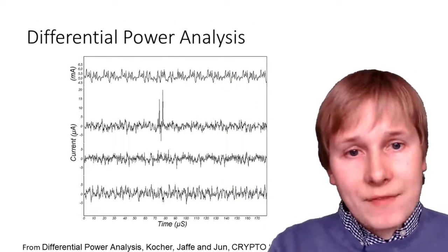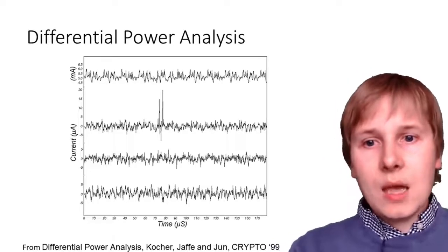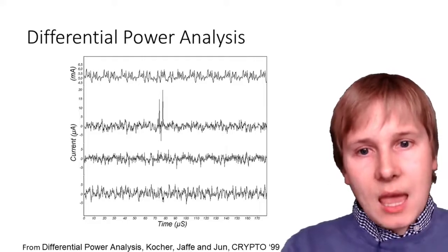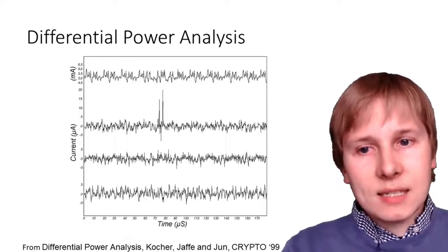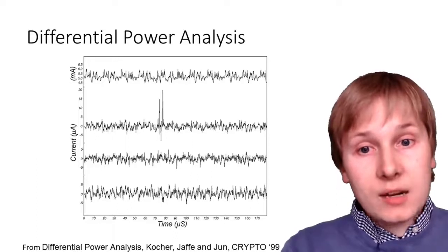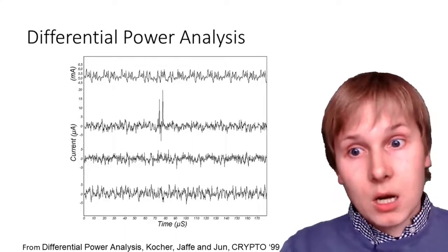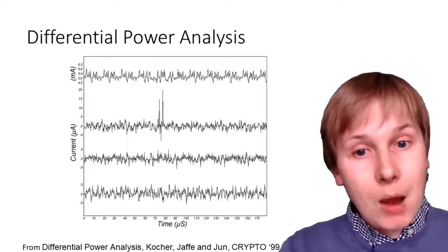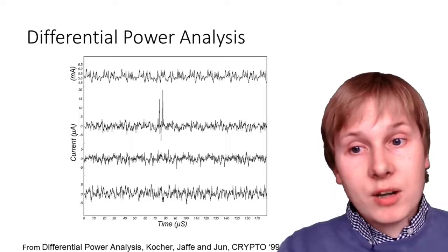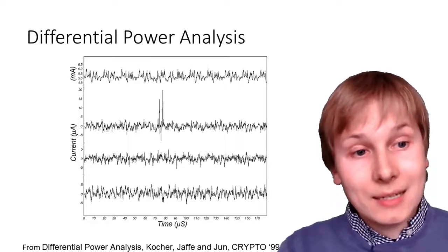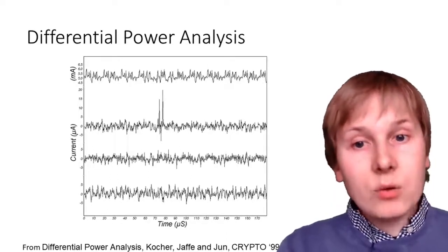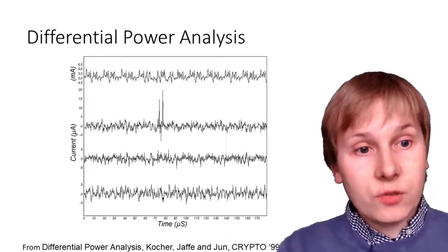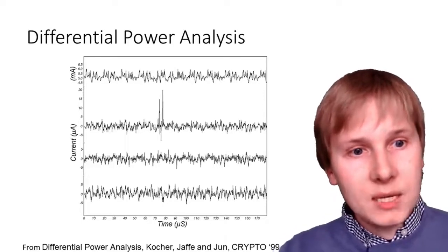Actually, cryptographic algorithms themselves can be particularly vulnerable to forms of differential power analysis. If the attacker knows or guesses the cipher implemented on a device, bearing in mind there are other good reasons to not roll your own crypto in any device that you make, then they can start correlating different power traces collected from operations with known either ciphertext or plaintext, either is fine, you don't need both, without knowing the exact implementation details, since it allows you to cancel out sources of noise. The differential part means that you cancel it out.